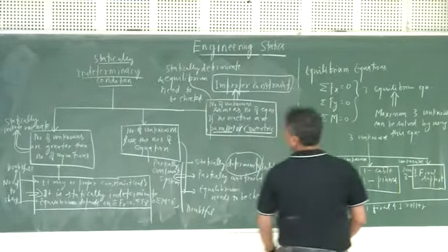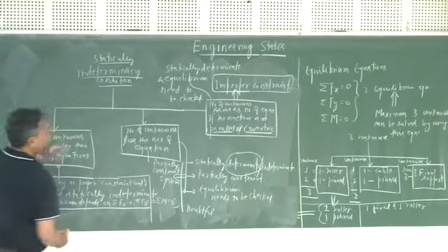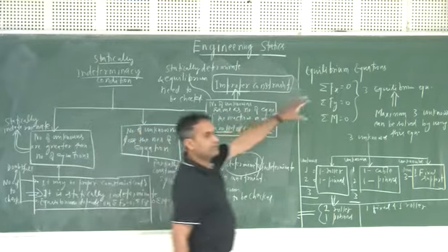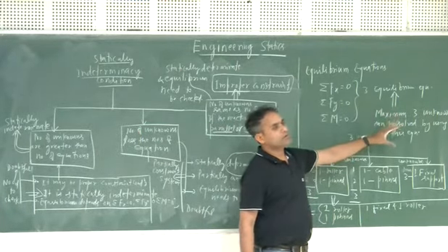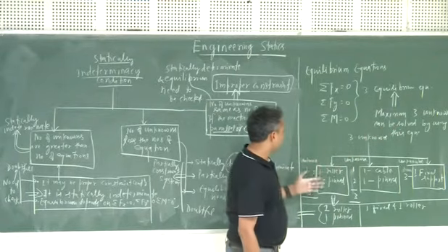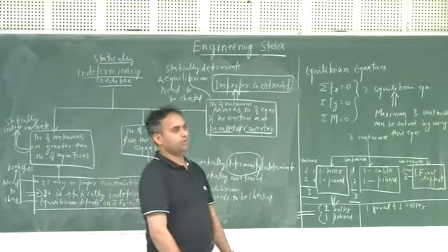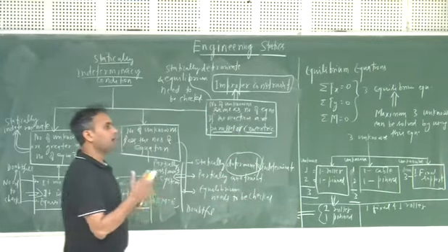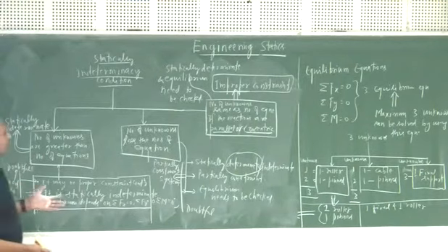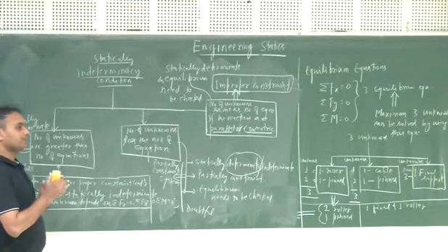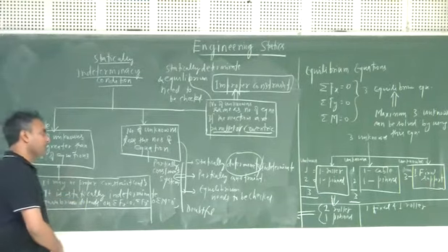So let me explain these things again. From here we found that the system will be in equilibrium if you have three unknowns coming out from the support system. You can select different kinds of support. Now, how you are providing the support? Three unknowns are there, but how you are putting them also defines whether the constraints are proper, improper or partially proper.